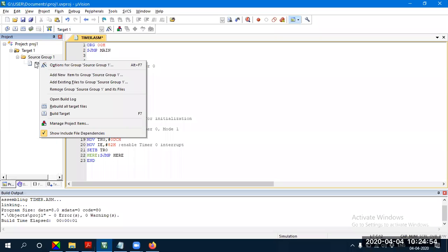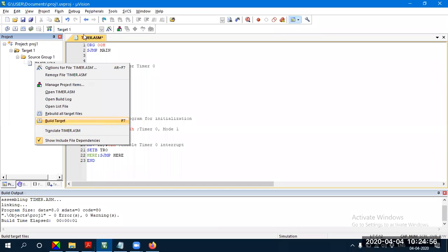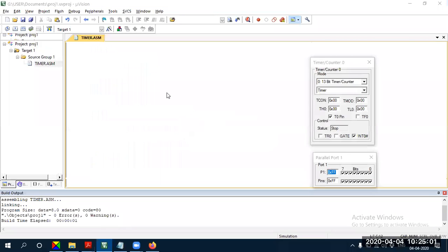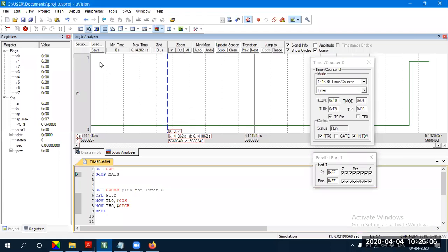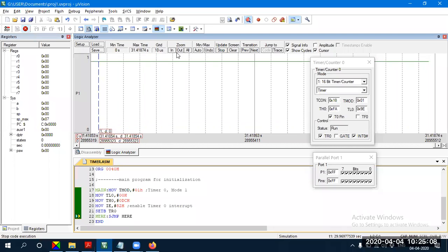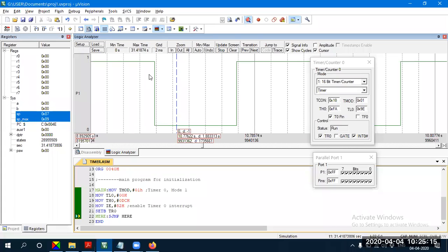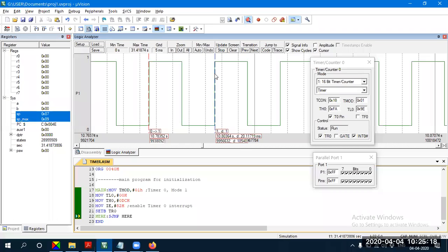Now this should generate a frequency of 50 hertz. Let us quickly look into this, and we can continue with the interrupt discussion. Debug, run. This is generating the waveform. I'll stop it, zoom all, take a particular waveform, zoom in. From this end to this end, the frequency is approximately 50 hertz, 49.9. Yes, it is 50 hertz. Maybe I had not properly placed the cursor. Now let us continue the discussion, guys.